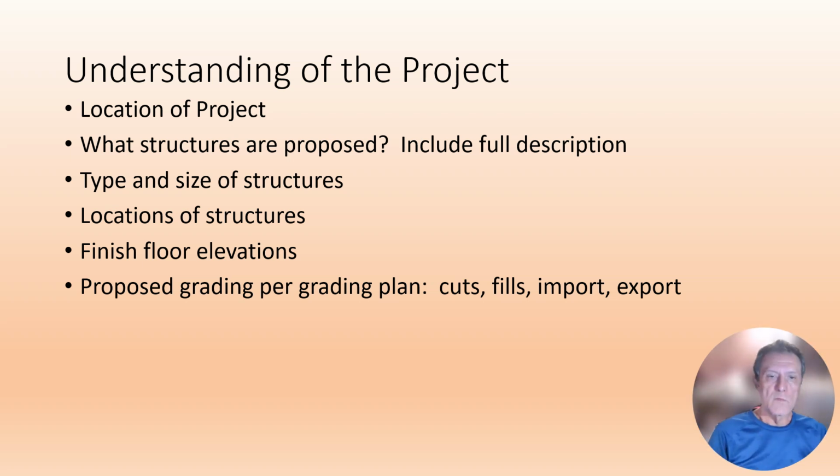What are the finished floor elevations going to be? Suppose you have a hilly site and you know what the finished floor elevations are going to be. Well, that means the site's either going to be cut down to that elevation or filled up to that elevation. And that requires obviously different types of earthwork and different types of exploration.